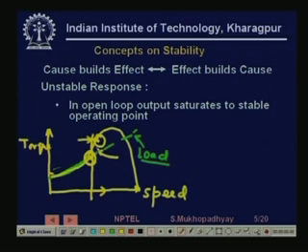So now you have extra torque. What will this extra torque do? It will increase the speed of the motor. So now the motor will go to this point where it has further extra torque, then it will come to, and finally it will eventually settle at this point. At this point again the generated motor torque is equal to the load torque, but in this other point, if something increases the speed and it comes to this point,